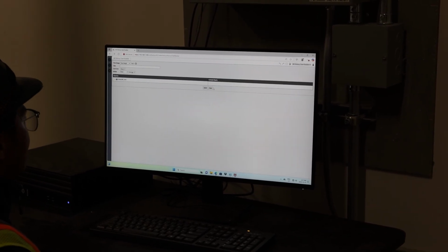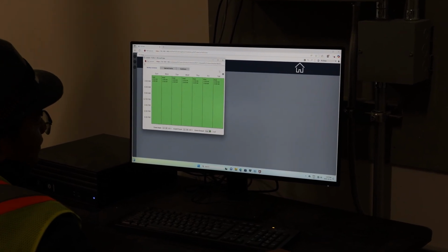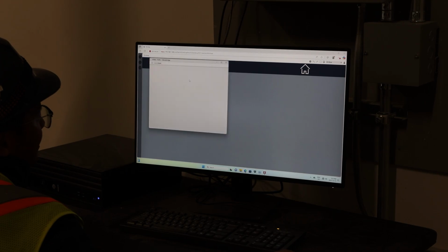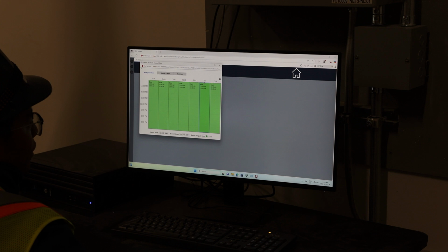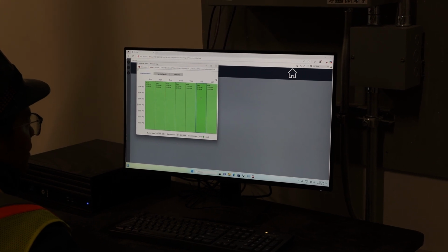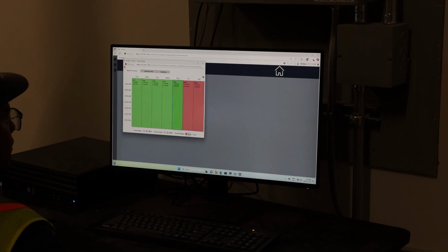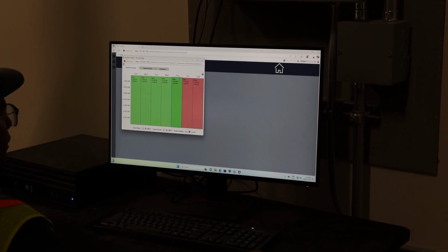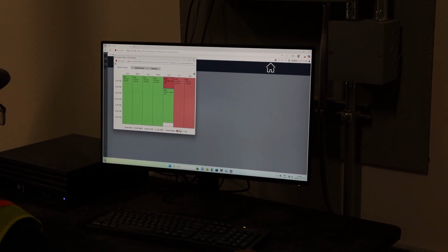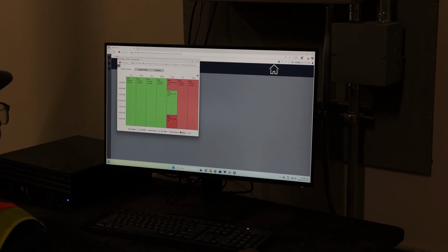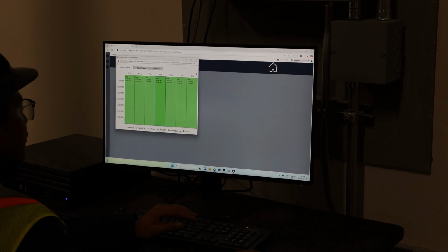Oh, the other thing I might want to show you is schedule. This is the ERV schedule, we want it 24/7, right? We want it running 24/7. Let's say fan coil 4, if you don't want it to run 24/7, if you want Friday to be turned off, you can just click here, false. And click here, false. And if you want to change the time range, you can just drag it. On here you can also drag another one, make this false. And after that you click save, it's saved. Yeah, that's how you change the schedule.